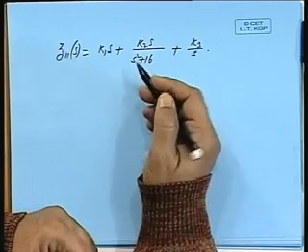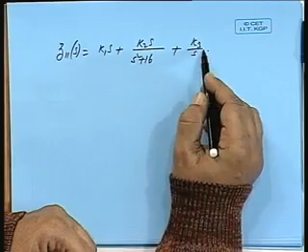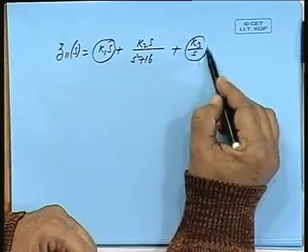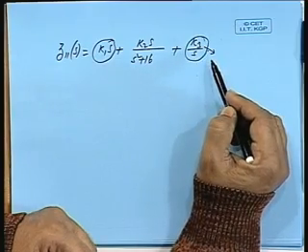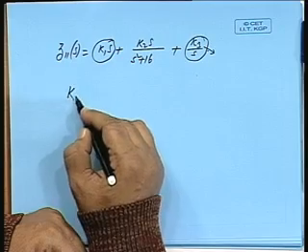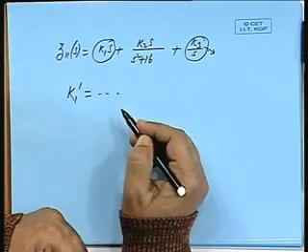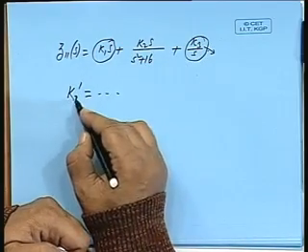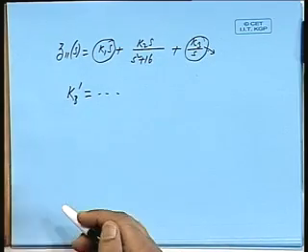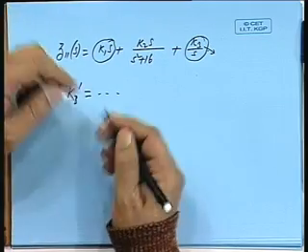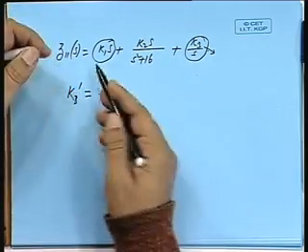While removing the pole partially, we were concentrating on K1 by S. Instead of that, it should have been K3 by S. From there you will get the value of K1 dashed, corresponding to the one that is to be removed, K3 dashed, and you will get the pole shifted. So, I would leave it to you for completion of this. After that, it is a very straightforward method.